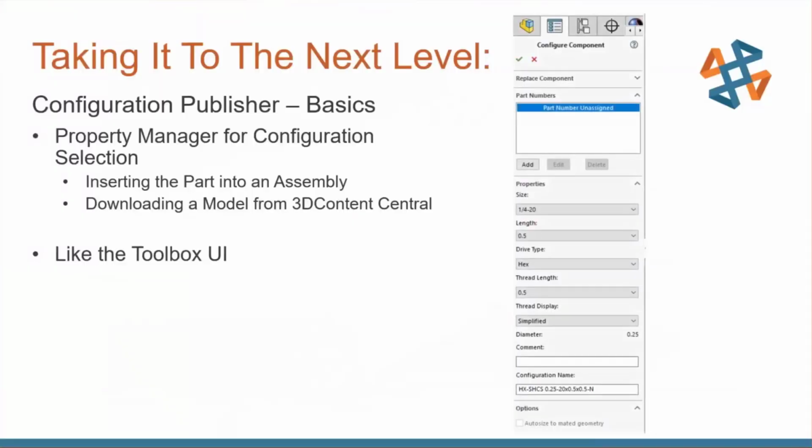But since we're limited on time, I'm going to jump into some other aspects that we can leverage configurations and design tables for, and that is the configuration publisher. This allows us to build and control a user interface so another user has an easier time selecting configurations to use in assemblies, for example. Very much like the Toolbox UI that I have a screenshot of there, but we're going to build one of these from scratch just so we can see how it works.